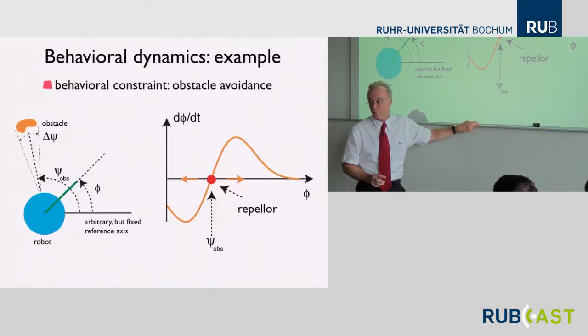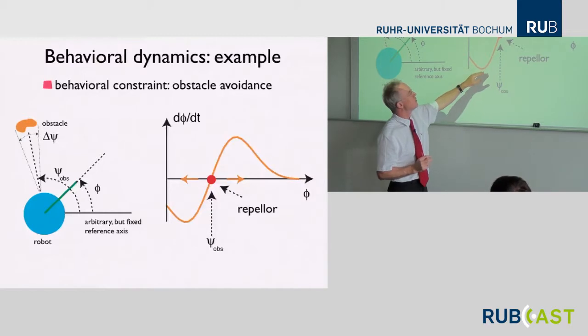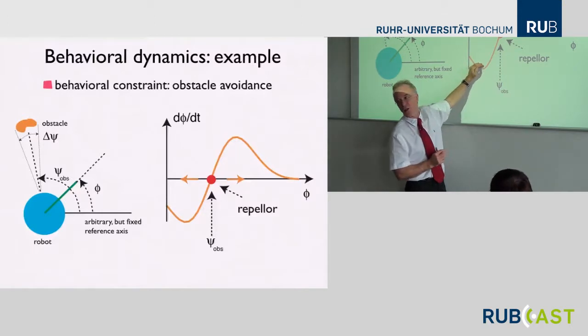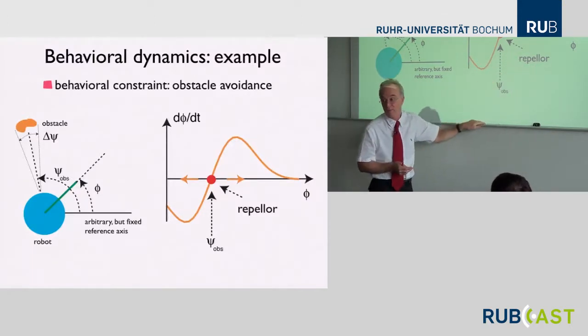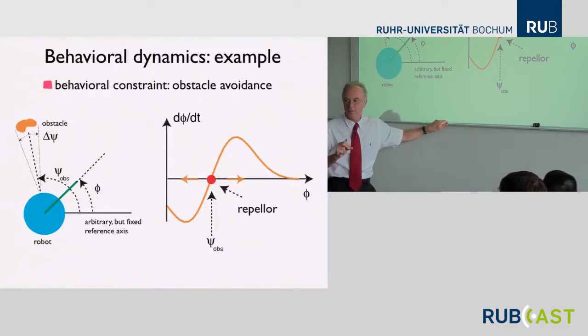And the answer lies in the experience of all of the students who then designed a clever system that somehow isn't like that and then found it work. It's really that if you don't do that, you have to connect the very negative rate of change on the left and the very positive in some way with the jump. And that jump will wreak havoc. That will make that somewhere sensor noise can put you a little bit to the right to get this positive turning rate. And then if you go a little bit to the left, there's some sensor noise. Go on the other side, you get a very negative turning rate. Your vehicle will make wild movements and will possibly crash.